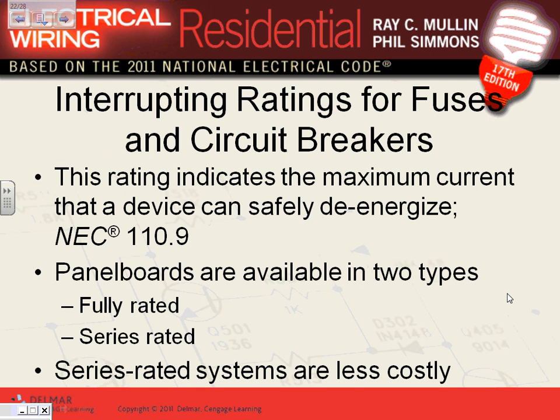What am I talking about labeling, guys? You have a circuit breaker like this, 100 amp. That's not enough to say 100 amp. What's the interrupting rating of this 100 amp? Well, the interrupting rating, if I just put this, it means it's 5,000 amp or less if I don't label it. Now, hopefully that wouldn't happen. So I need to go there and put 22.5 kiloamp. So this circuit breaker now can handle up to 22.5 thousand amps or 22.5 kiloamps, a short circuit, ground fault, and so forth. Any question, guys, about circuit breakers, thermal?